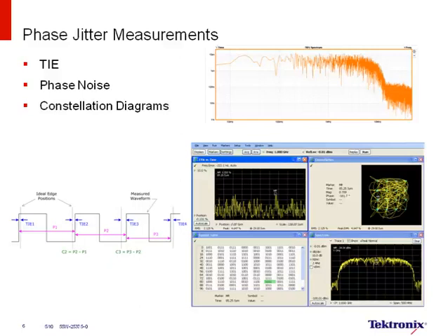You want to make sure the loop bandwidth matches your receiver. You want to make sure the peaking and damping factor match your receiver. You want to make sure the PLL order matches the receiver. So that's one part. Remember, though, this is still an estimate because these functions you see here are linear estimations, and most receivers are much more complex than these setups, okay?